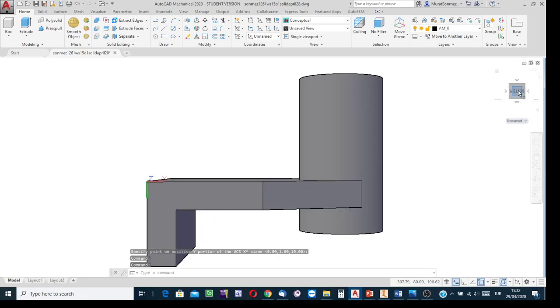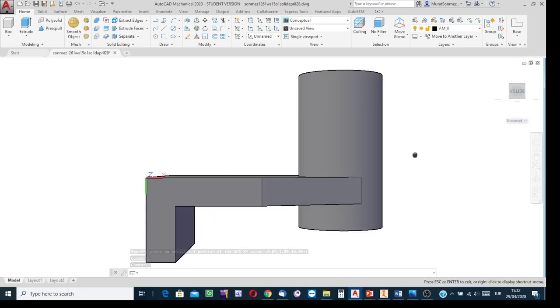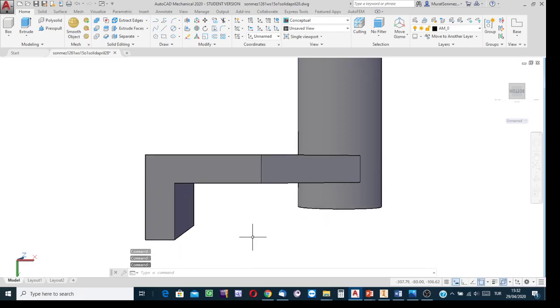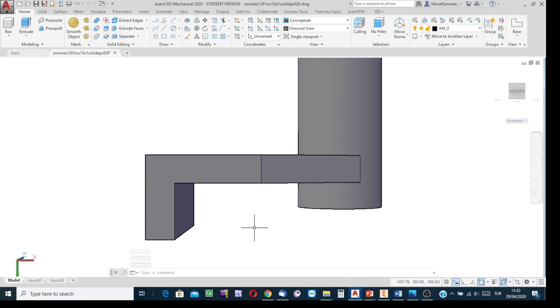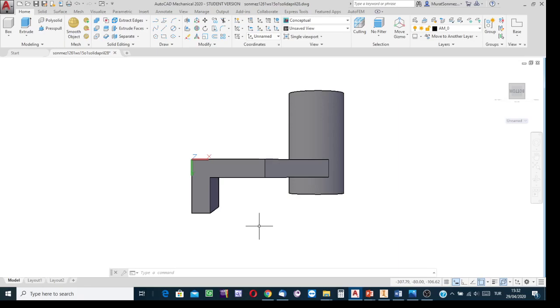Although I clicked on the surface of the viewing cube and expected to see this profile surface edge-on, you see the model is in perspective appearance. It is misleading to see the model in perspective appearance, so see the model orthographically.